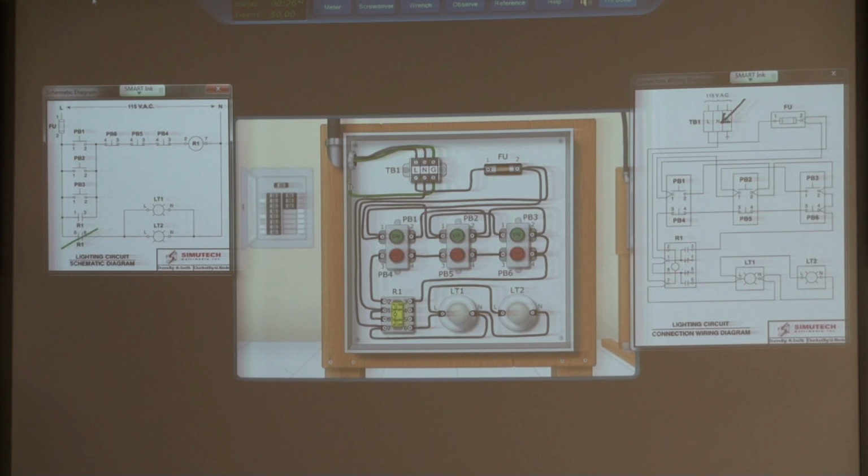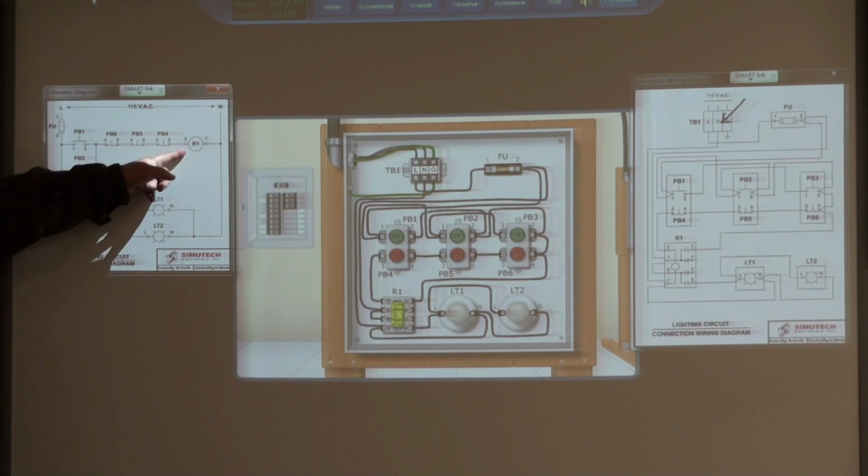So very good way to understand it. Hmm? Run that by me one more time. It's the same thing as 1 and 2. That's right, they're permanently on. And 3. They're permanently on, and when there's nothing to turn them off, 4, 5, or 6, it's not turned off because the path is, because this contact is no longer controlled by the relay.